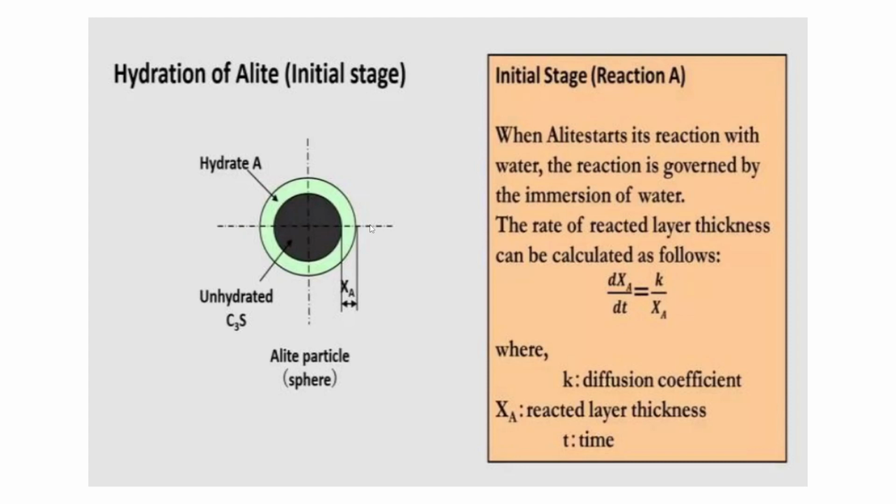Curing is basically the stage where, after mixing and after the concrete has been cast, it is stored in a wet place so that the hydration is completed. Hydration is directly associated with the gain in strength and the proper binding. Hydration is basically of alite, because standard cement contains the highest concentration of alite, which is C3S.